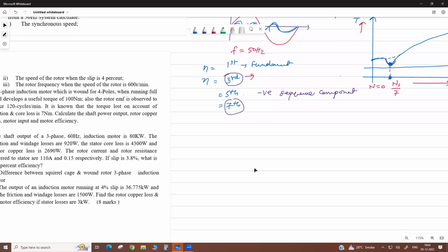Basically we are chopping the sinusoidal voltage. Then we get it again through an inverter. So actually we do not get a pure sinusoidal. Even if we use pulse width modulation to make a pure sinusoidal, there are harmonics in that. So actually this is the disadvantage of your VFD.